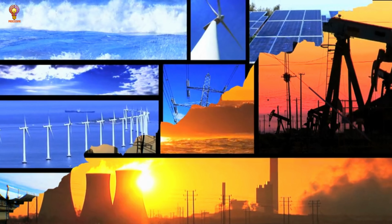5. Solar power plants. Solar power plants use sunlight to generate electricity, either through photovoltaic (PV) panels or solar thermal technology. Photovoltaic (PV) solar power process. Sunlight absorption: solar panels absorb sunlight, exciting electrons in silicon cells. Electricity generation: this generates direct current (DC) electricity. Power transmission: the electricity is sent to the grid for distribution.